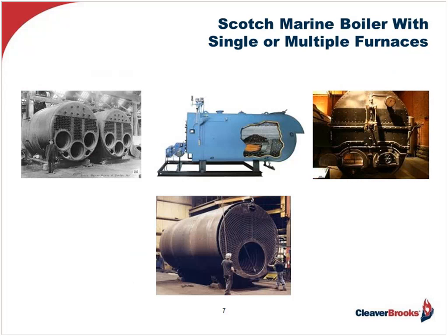So the Titanic's boilers were Firetube boilers, also referred to, as you know, as Scotch Marine. And as you can see, could be constructed to include multiple furnaces, such as the Titanic had, or a single furnace, as also shown in the picture on the screen in the center. However, in any case, you have a single shell housing furnace or furnaces, and then you have tubes, and they're all surrounded by water.